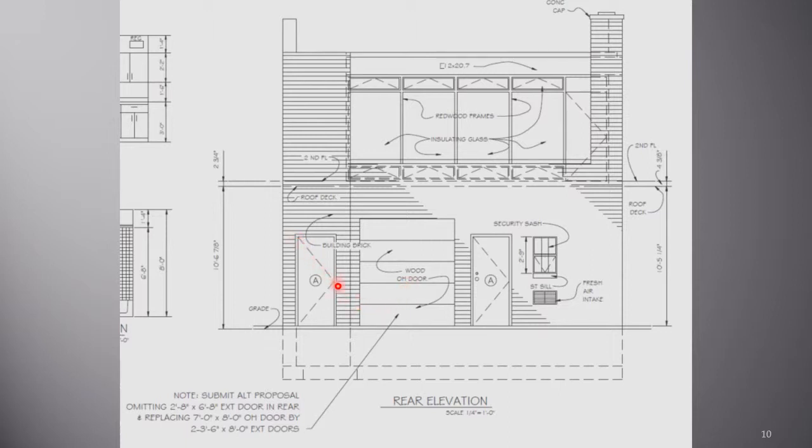The little dashed lines culminating in a point here indicate that this door is hinged at this point. So the doorknob would be here and the door would open out and the hinges would be along this edge. I have a window here which has the V shape pointing down, which would indicate that this window opens out along a hinge at this point.